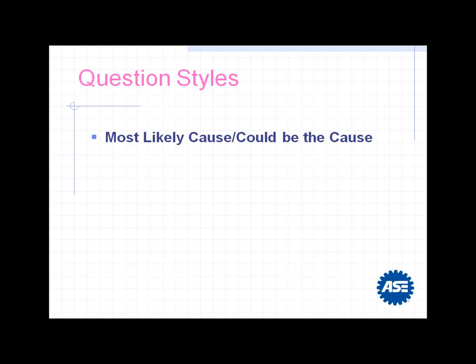Well, as we know, in a diagnostic scenario, many things can cause the same symptom, okay? A misfire, if we're going for a misfire, we could have a fouled spark plug, an open plug wire, a burned valve, all kinds of things could cause the symptom of a misfire. But in an ASE question, we ask you which of these, okay? Because of these, there's going to be one thing that will cause it and three that won't, and we're testing your knowledge of those situations to see if you understand the difference and which of those could be the cause, okay? So just want you to understand the distinction.